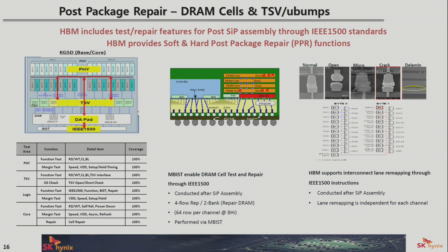I talked about being able to test the HBM device. The figure on the left-hand side here shows that you're able to test the device using an IEEE 1500 interface. There are test flows that are defined at JEDEC to do this.